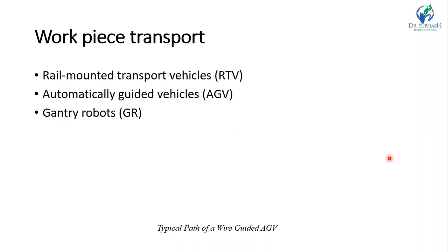workpieces. So this of course requires robot grippers which suit the workpiece geometry. Further, the components should not have large dimensions and their weight should be small. So it may be noted that in this case, several of the expensive fixtures which would otherwise be used to mount the workpiece on the pallets are not required.